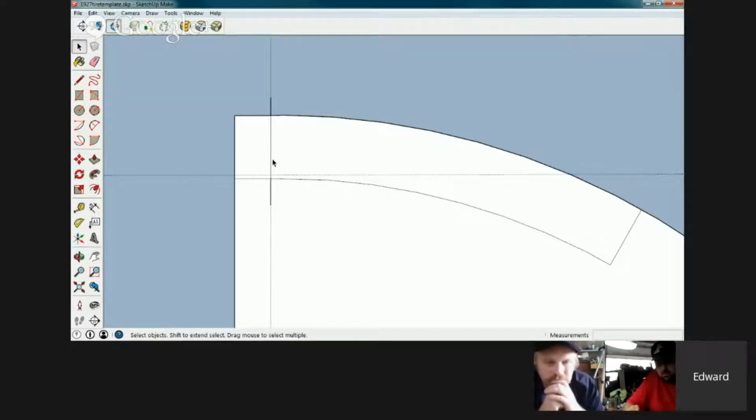Now I want to move this 0.11, I say. That's fine, because we're saying our minimum detail is 0.1 millimeter, so I'm just going a little bit more just so the software is happy. Okay? And I'm just going to draw a vertical line.